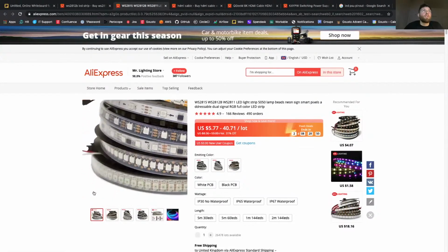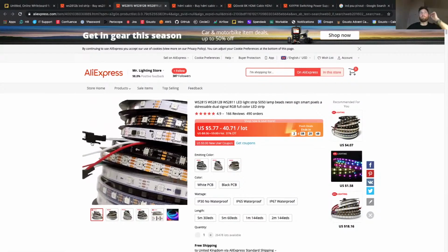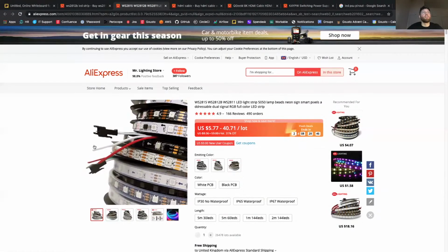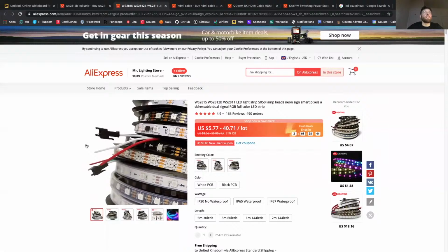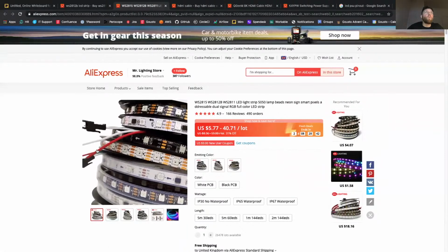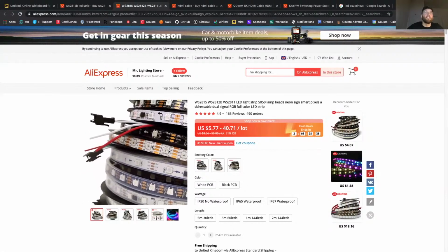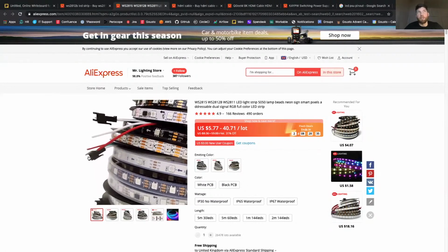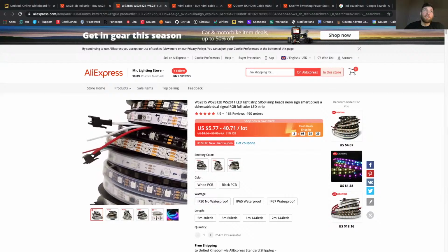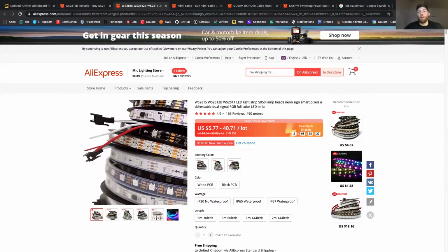You might be able to start seeing them there, but each of these strips starts with a red wire, a white wire, and a green wire, and then these connector units, which happen to be called JST connectors. Okay, and you need to know exactly what each of those wires does, and you need to have a method of connecting them into your circuit appropriately.